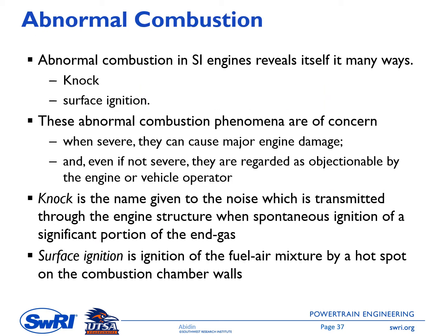Next topic is abnormal combustion. In spark ignition engines, we have knock and surface ignition. These abnormal combustion phenomena are of concern. When severe, they can cause major engine damage. I have an example of the engine damage due to this abnormal combustion in the next slide. And even if not severe, they are regarded as objectionable by the engine or vehicle operator.